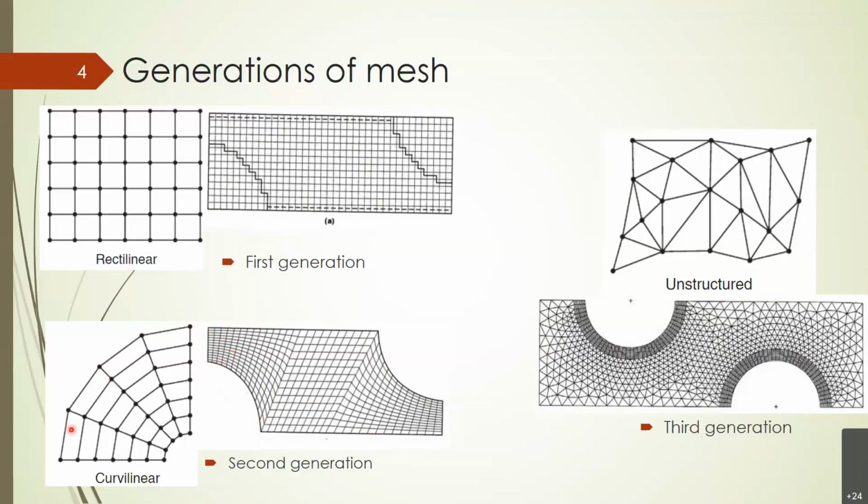Let's take this semi-hemisphere, this quarter here. Assume that we extend the mesh here. This is possible, but it will be problematic because, as you see, everything ends at one point where we have to define the directions. If everything goes to one point, there will be some problem. If I'm not mistaken, this is known as singularity, which is not desired.